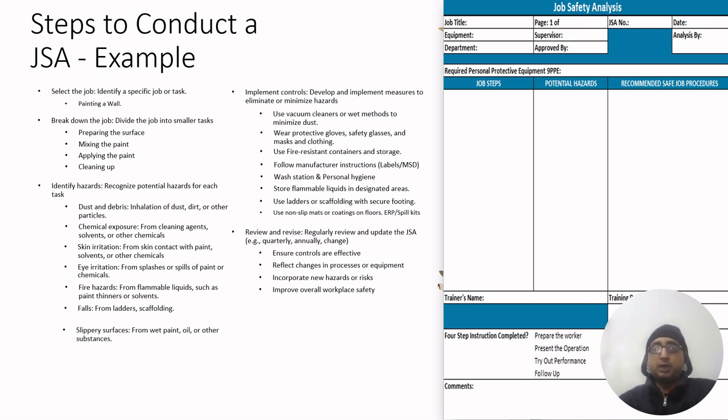Simply, first of all, make sure that your surface is stable and firm, and it can bear the load. And then, to make sure that nobody is under the load, make sure all the area is barricaded, exclusion zones are defined, and no one is under the load, so the crush hazard can be avoided. Similarly, when you are putting the load down, put it down smoothly, not hurriedly, so the load itself is not damaged.